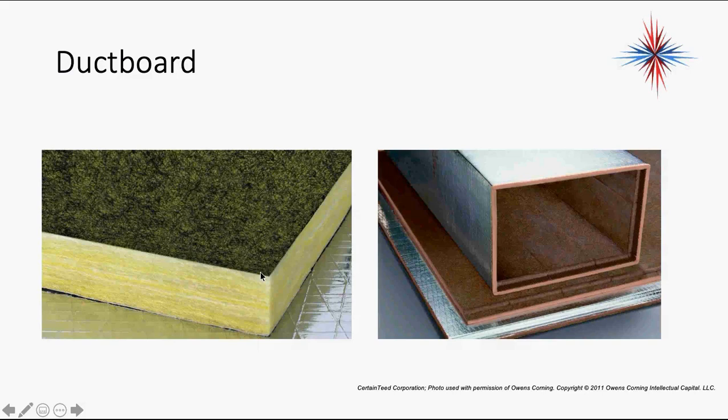Down in Florida here, and once you get south of Georgia, this is all you see. Georgia and south, it's all you see. Around the mid-southwest, this is all you see. It's duct board. Okay, cheap install, because you can basically construct your ductwork on site. You don't need a sheet metal shop. You don't need specialized people to do sheet metal. Okay, you can avoid the sheet metal union that controls a lot of the area with ductwork. So you can install duct board for very inexpensive installs.